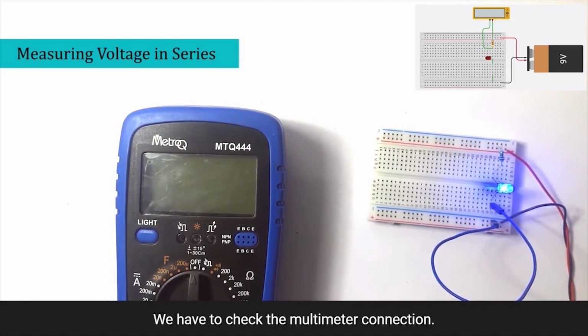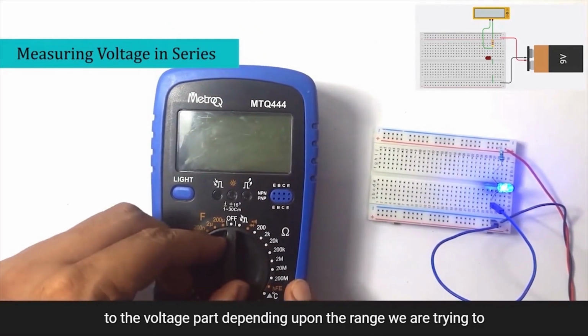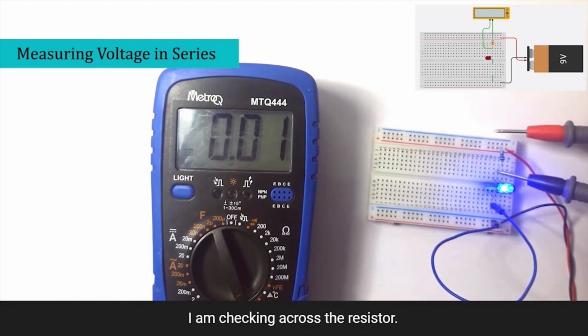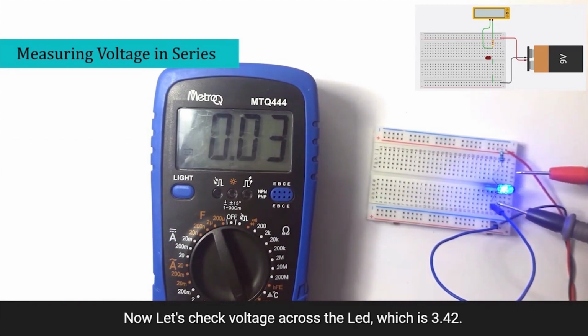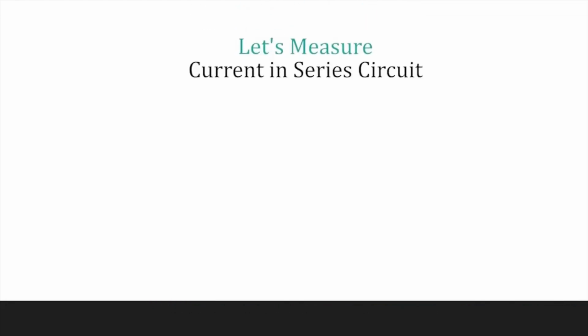First, we have to check the multimeter connection. The positive should be at the V and the negative should be at the common. And now we'll shift our knob to the voltage part depending upon the range we are trying to check. So now I'll connect for the first terminal. You can easily see I am checking across the resistor. The voltage across the resistor is 4.65. Now let's check voltage across the LED, which is 3.42. So as we can see, the voltage across the terminals is dropping.